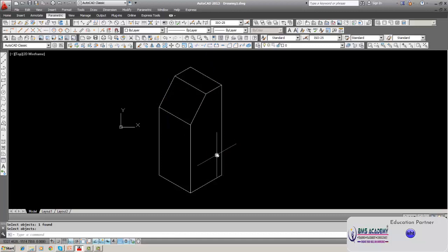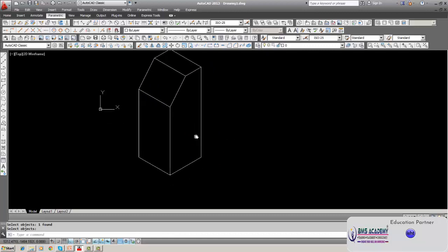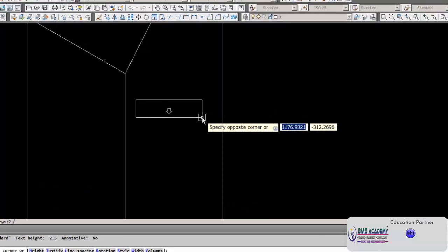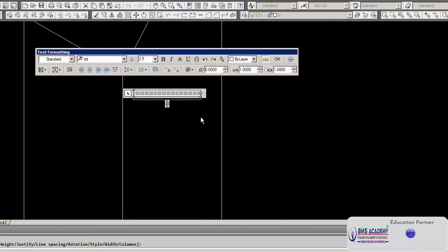I have already told you about isocircle. Now I will explain drawing the text. So the text command, you know the text which we did in the previous class. On this space you want to draw the text. Here the orientation is 30 degrees. So you have to enter the oblique angle for the text. We change it to 30. We'll see whether it is 30 or minus. First we'll change to 30 and you make this a little bit bigger. Now you can type the text as it is.